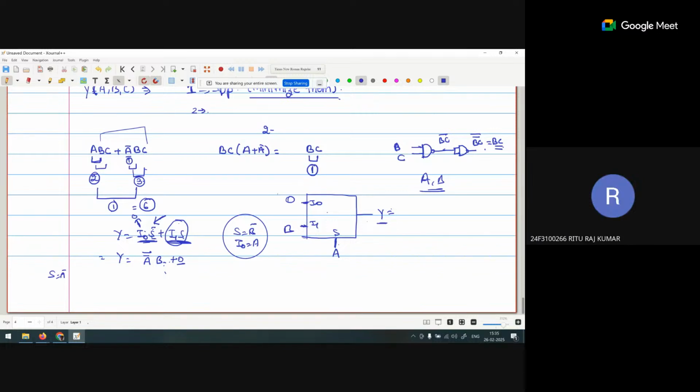Because I created this gate and you created A0 as A, I just saw that there are different ways. If we are not defining the exact statement in the question, we can't say that only A and B inputs are available. There are three ways to create an AND gate using a 2x1 mux.